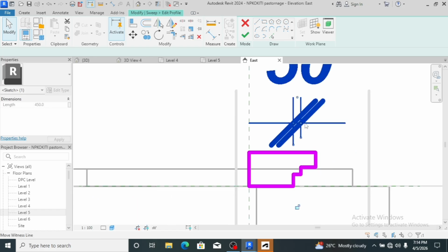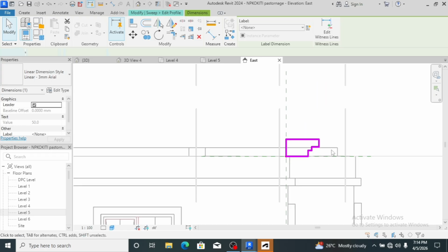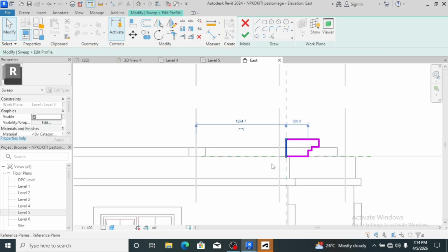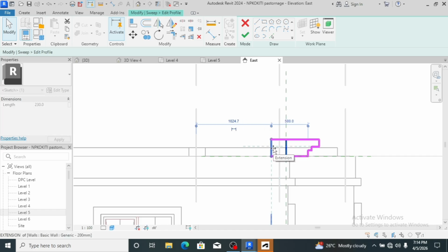Now let me remove this, delete. Now I want to project to the edge of the wall, at the extreme, the external peak. So from that external peak, you as an architect are telling the engineer that from this peak to this place is 300. So now from here, you drag to this point. You have picked your wall. It's already highlighting the wall, so you drop it there.